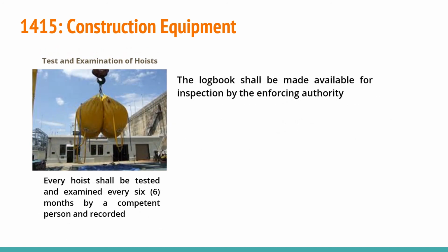Test and examination of hoists. Every hoist must be tested and examined every 6 months to ensure its functionality and safety. It must be done by a competent person and recorded in a logbook that will be made available for future inspection.